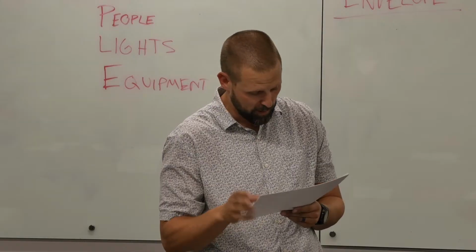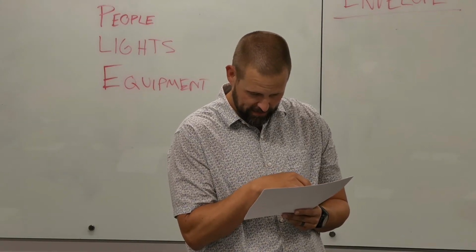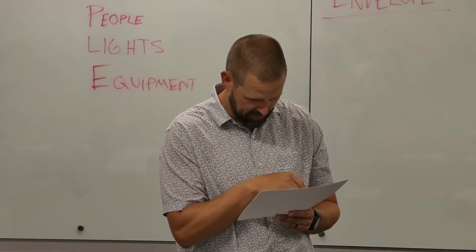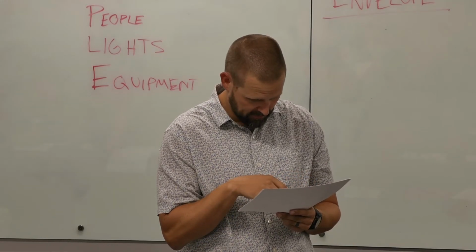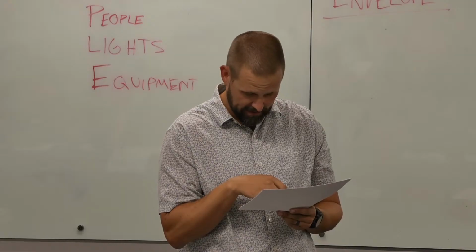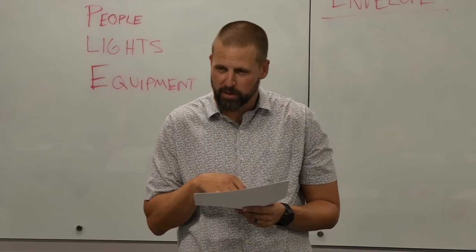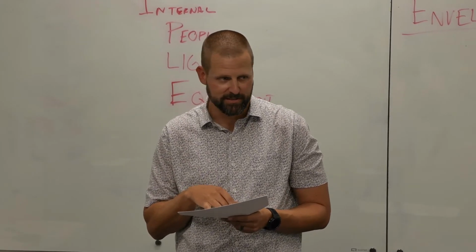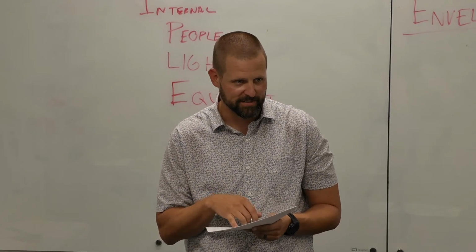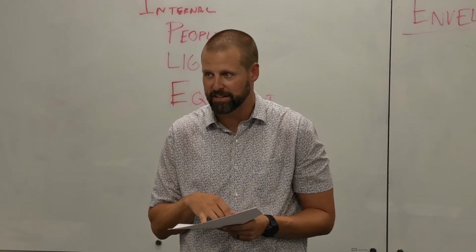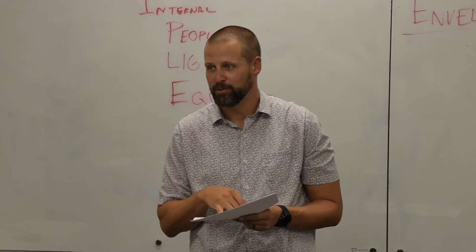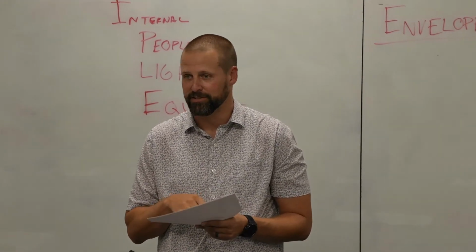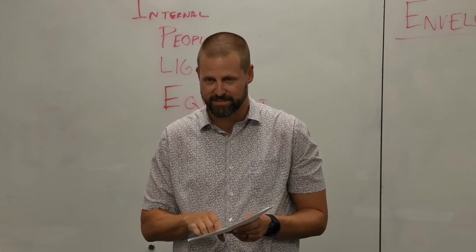If you go to the design wet bulb column, after cooling, the 0.1% design wet bulb for Los Angeles County is 72. And the wet bulb temperature in LA has been much higher than 72 these past 2 weeks. So anyone who has facilities that are dehumidifying is hurting because they're probably not designed above 72.